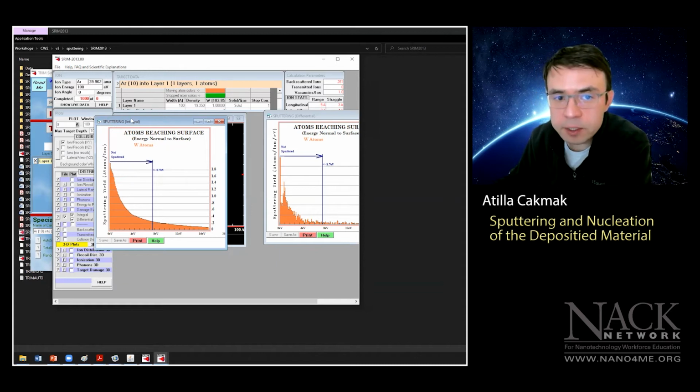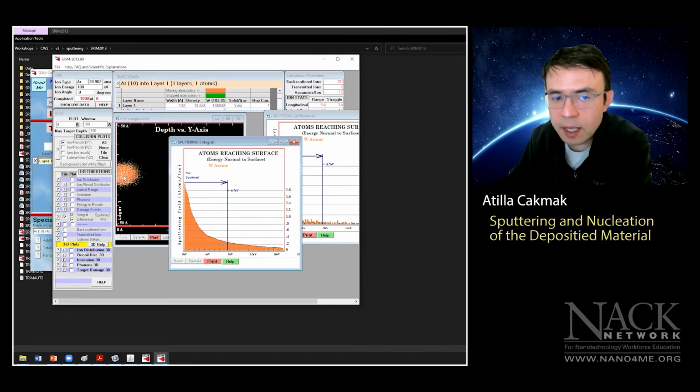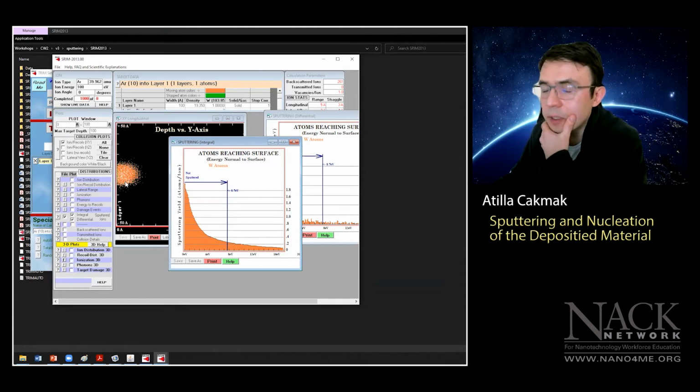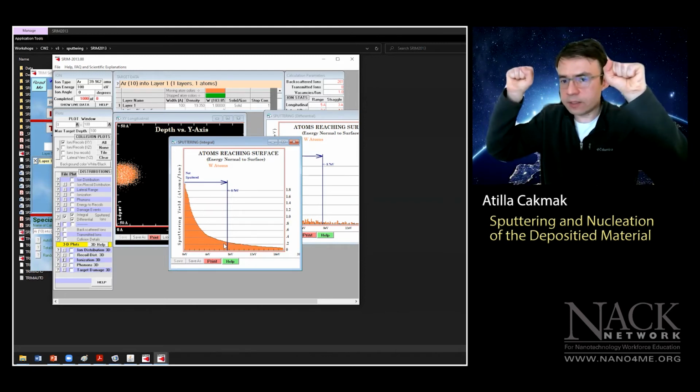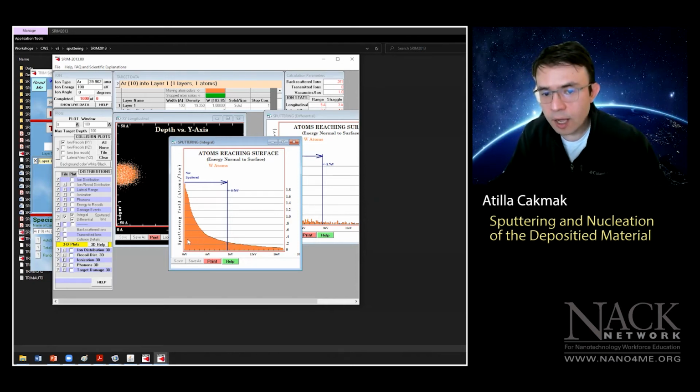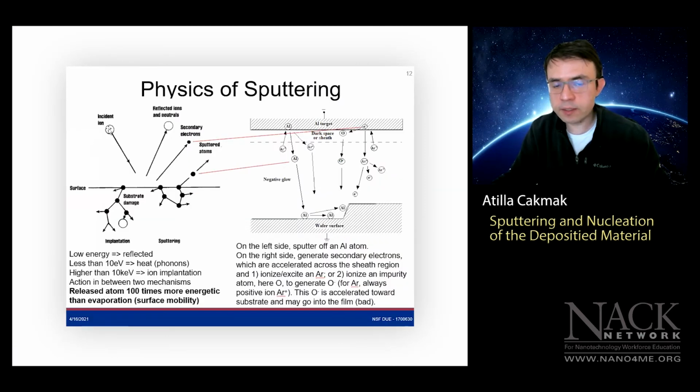Why is that taking place? Because we're going to attack the surface from outside with an external power supply, and we're going to try to counteract the binding energy of the tungsten particles. Those are chemically bound to each other, right? The tungsten elements are bound to each other. So up to this side, it's still tied up to the surface. That's why it's not sputtered off. But beyond this side, if the tungsten that is speeded up by the incoming ion has enough energy delivered from the incident argon ion, and that reaches beyond that 8.7 electron volts in this case, we might sputter off this tungsten.